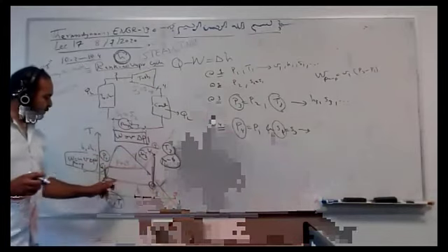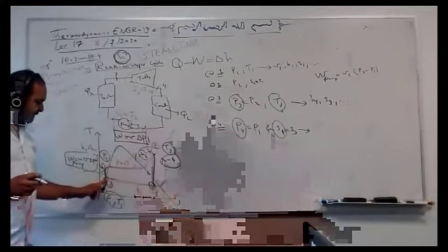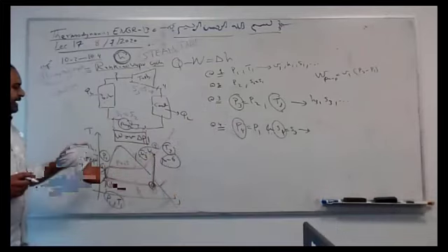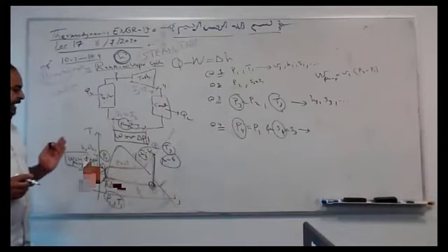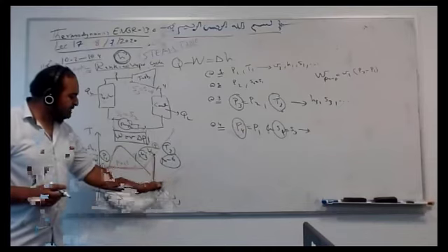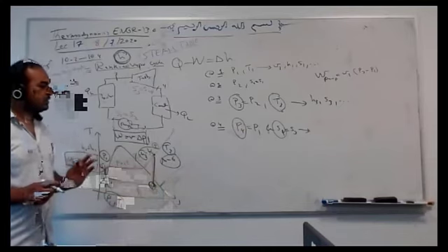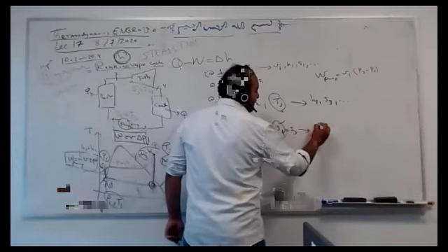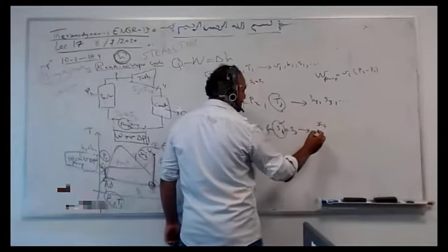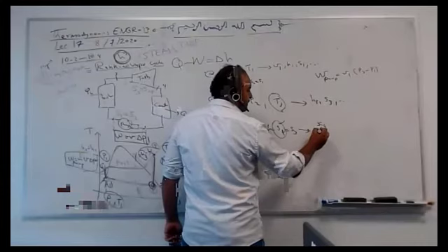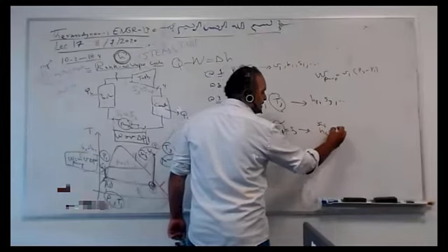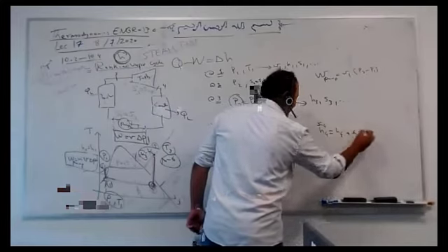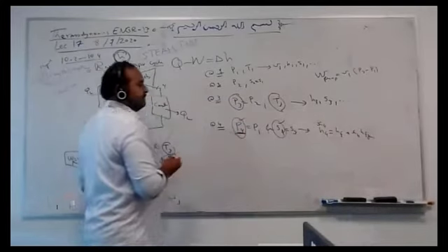If S4 was between SF and SG of this pressure line, it's a saturated mixture. If it's greater, superheated. If it's equal here, it's saturated vapor, and so on. So from this and this, you can get, for example, quality if it's a mixture. You can get, for example, enthalpy, which is HF plus X HFG at this pressure.